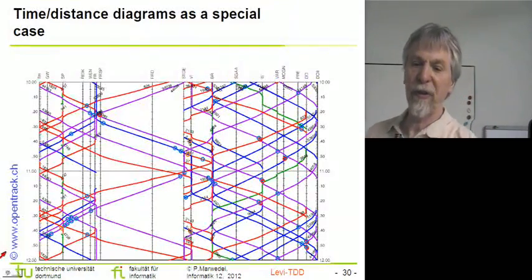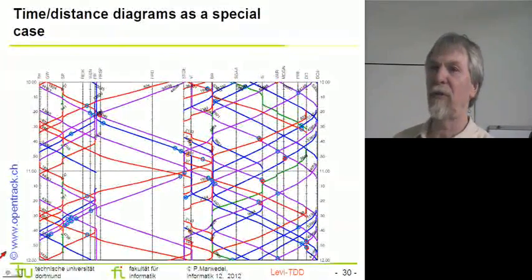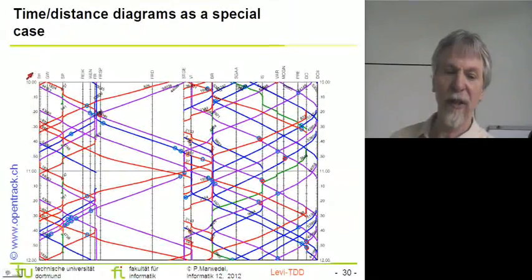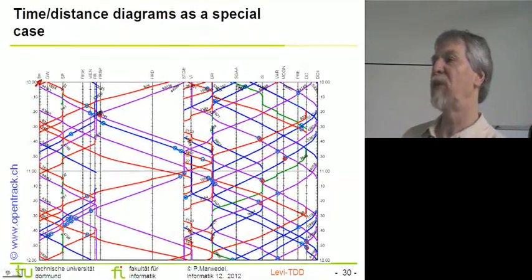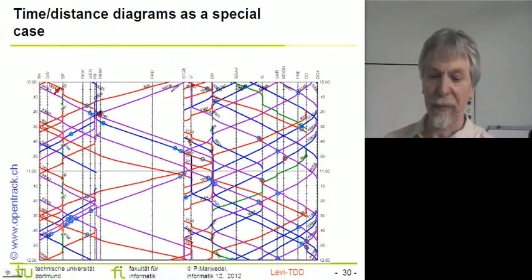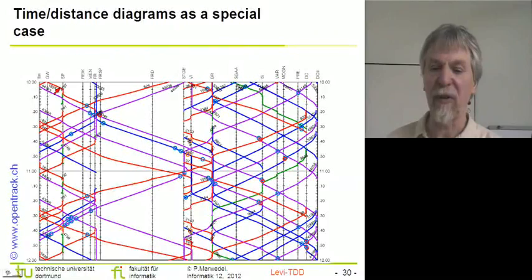We can go a little further into the same direction by now really looking at the way that the schedules of rail systems are represented. They are typically represented as so-called time-distance diagrams. And in the time-distance diagram, in the vertical direction, we now really have real time. So we see real time written down there in the vertical dimension. And we might even have a situation where in the horizontal dimension, we really have real distances. In this case, we only see some symbolic distances. So in this diagram, we see a good set of trains that are running somewhere in Switzerland.